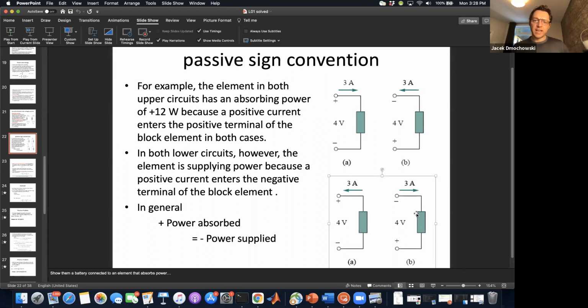So another thing that I always say in this course is that if you can trace from any one point in a circuit to another without going past any device, the voltage at those 2 points is equivalent. So in other words, the voltage here is equivalent to the voltage here, and the voltage here is equivalent to the voltage here. Right? So if you can trace your finger along any 2 points in a circuit without going through any elements, then those 2 points are the same voltage.